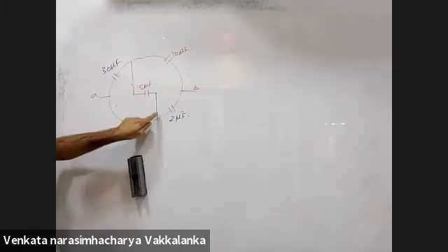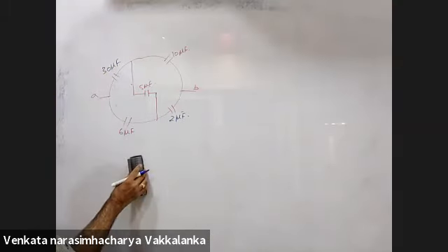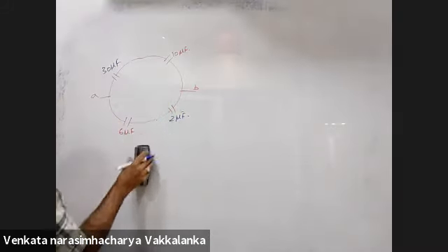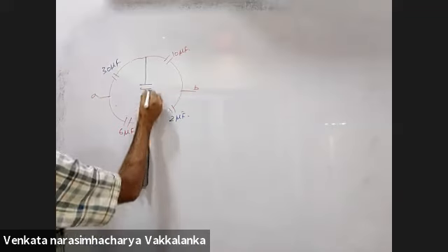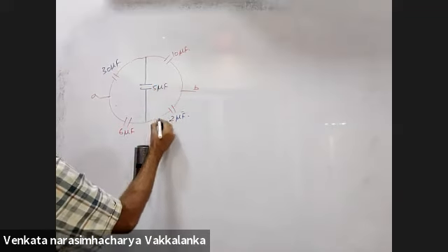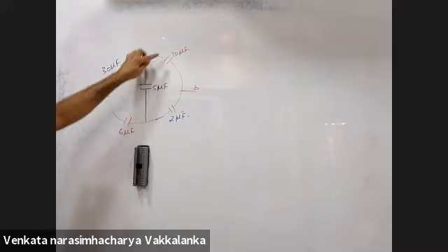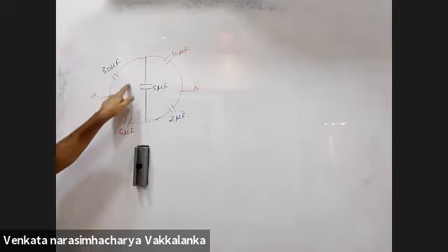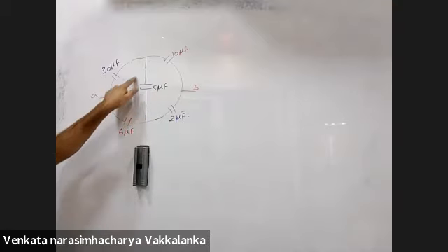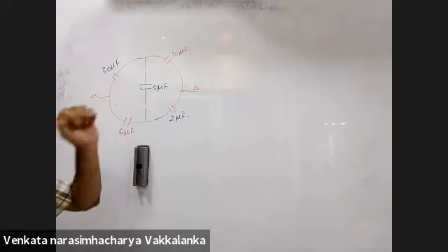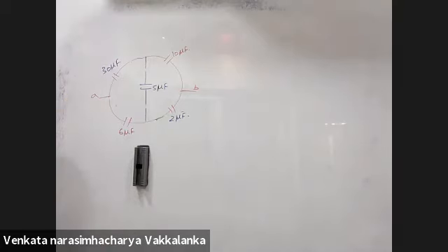Now we don't need designs here. Let us make it straight. 5 microfarads, we don't need a design. Let's make it straight. 30 by 6 is equal to 10 by 2. The 5 microfarad capacitor is null and void. 30 and 10 are in series. 6 and 2 are in series. They both are in parallel. Equivalent capacitance is 9 microfarads.